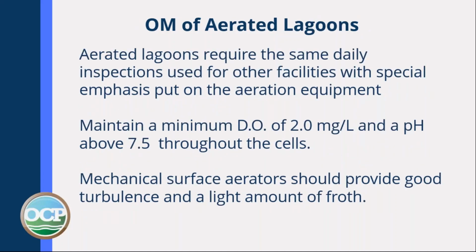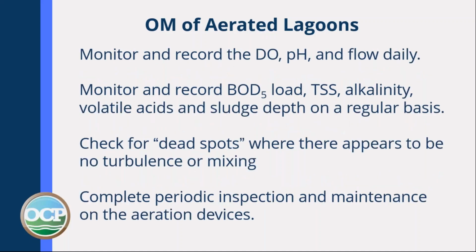Aerated lagoons require the same daily inspections used for other facilities, with special emphasis put on the aeration equipment. Maintain a minimum DO of 2.0 milligrams per liter and a pH above 7.5 throughout the cells. Mechanical surface aerators should provide good turbulence and a light amount of froth. Monitor and record the DO, pH, and influent and effluent flow daily.